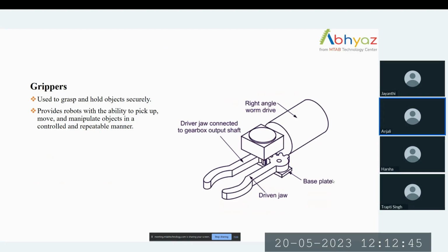Here are different types of grippers available to use. Some gripper designs are just like human hands, which have five fingers, but it's not always the same case. There are grippers with two or three fingers. There are different types of mechanical grippers, vacuum grippers, magnetic grippers, and servo grippers. Vacuum grippers use suction cups to grab and hold things, but magnetic grippers use a magnetic field to hold ferromagnetic items such as steel plates.